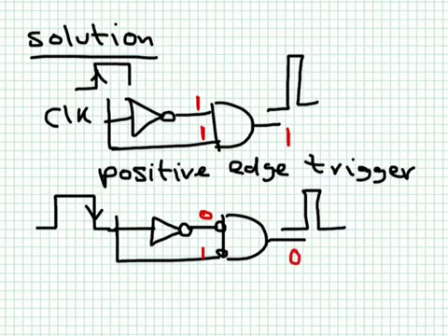Okay, now we have a falling edge. It means that the output suddenly changed to 0. So now the condition has changed. So this one here becomes 0. But this input will take some time because of the inverter. All electronic gates have some delay. Your output becomes 0, but it will take some time for this output here to change from 0 to 1 as a result of the change that happened from 1 to 0 here.